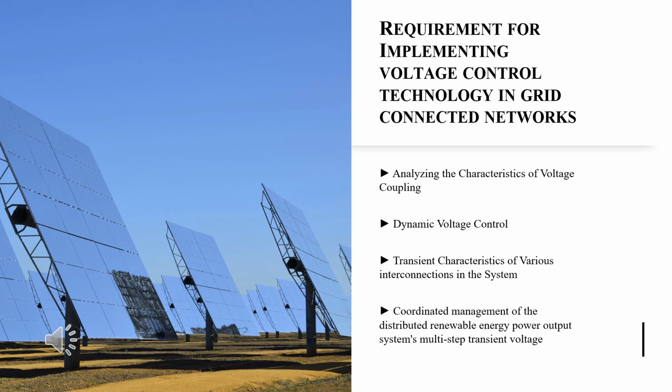Dynamic voltage control is another requirement. It is essential to have clearly stated response mechanisms in place coupled with efficient distributed voltage controller coordination to provide stability, particularly voltage stability. Voltage instability and unnecessary regulations are avoided in this way. Through controller coordination, this is especially crucial in renewable energy systems with several devices, guaranteeing voltage quality and reactive power balance.